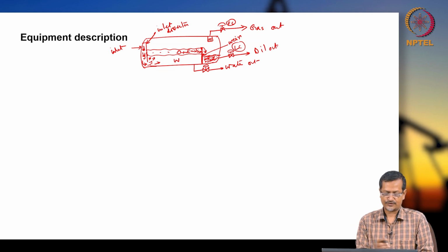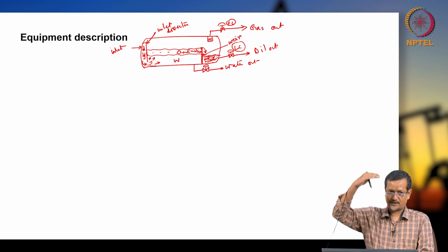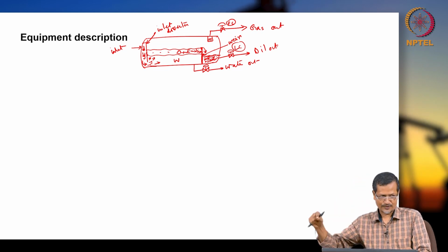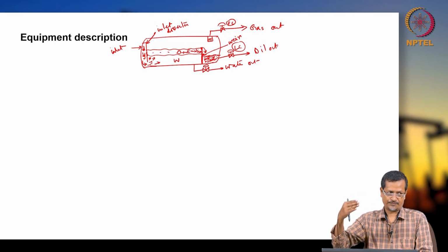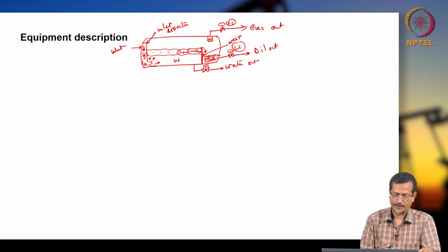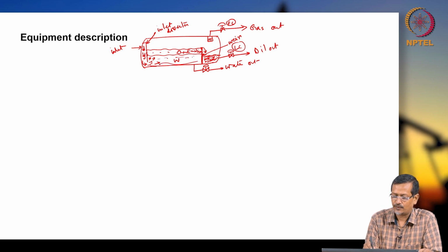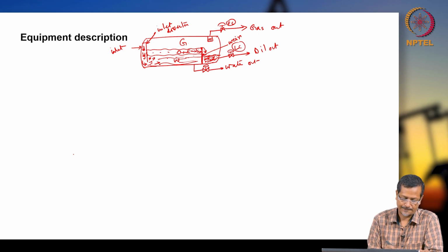If oil is not there in this area, again you stop the dump valve, allow the oil level to go up, and again open it, going out. So continuously you are doing this job. Sometimes you are stopping, sometimes you are opening, stopping, opening, so that work will go on. Okay, this is water, and this upper one is gas.